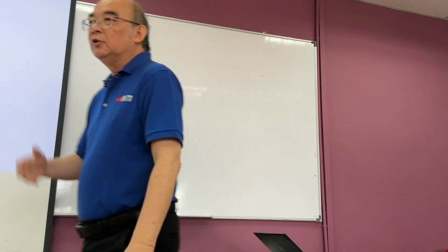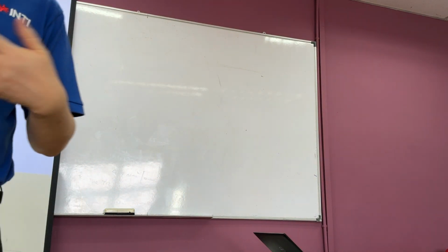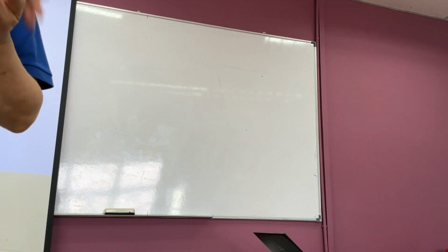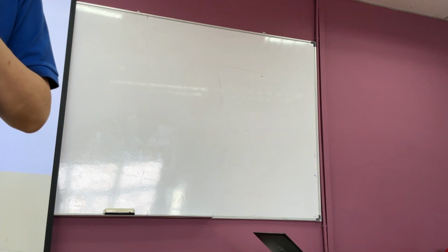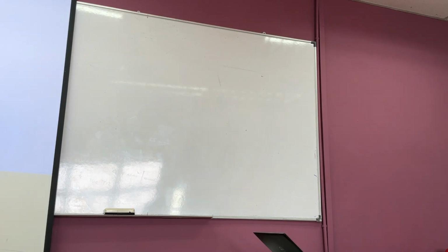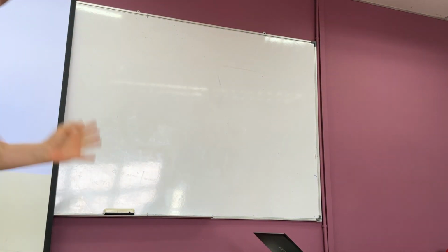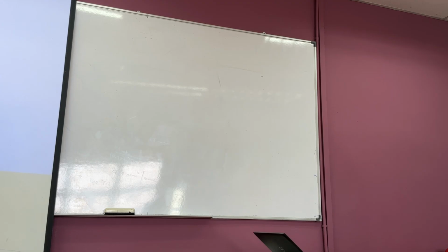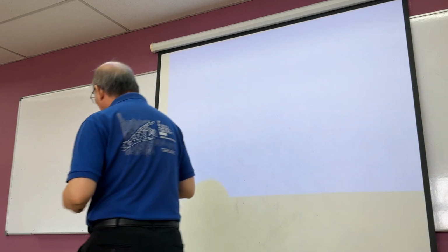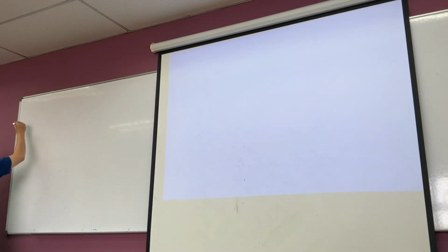Okay, so after you finish the shear wall, then we will dismiss, and then you go and study for your final exam for the afternoon. Okay. First of all, the shear wall. We have 3 load cases, right? 1.2 dead load, live load, wind load, or 1.4, and so forth, right? So I just tell you that in the exam, you are going to work with a 1.2 dead load, live load, and wind load.